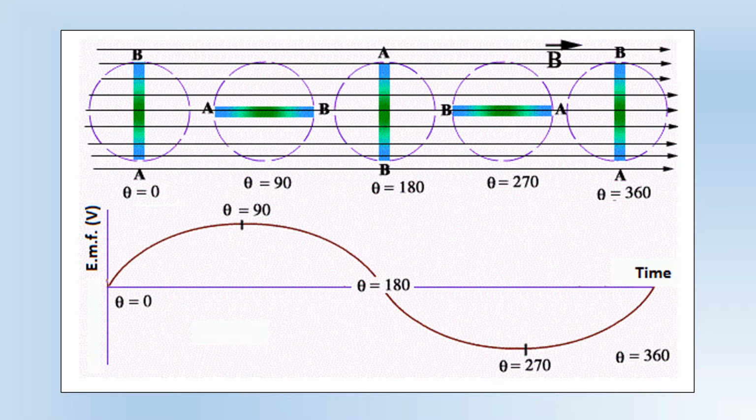Let's look at what the whole thing looks like. So if we have a motor do a complete rotation, this is the waveform that we produce. So this first one here, these points are moving, so this one corresponds with this point over here. So A and B, remember, are moving parallel to the field, and therefore no flux lines are cut, so we get no EMF.